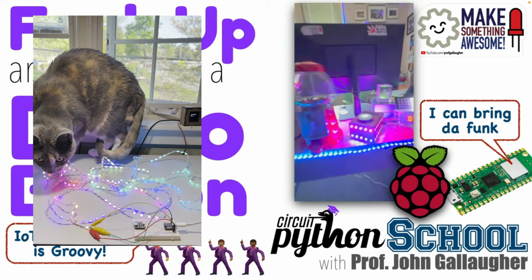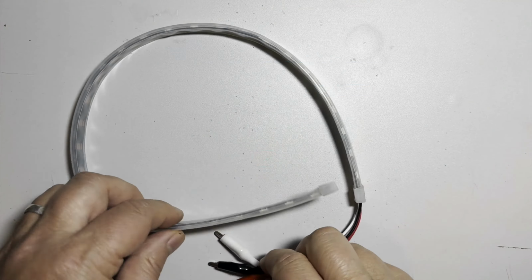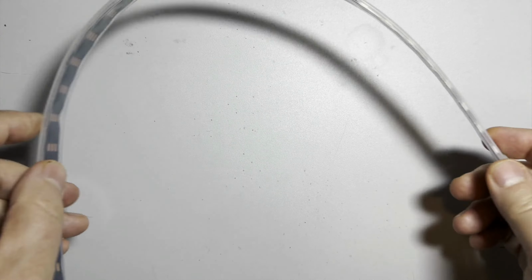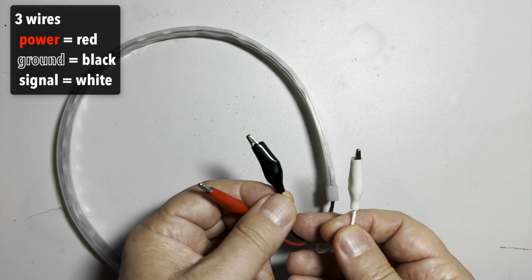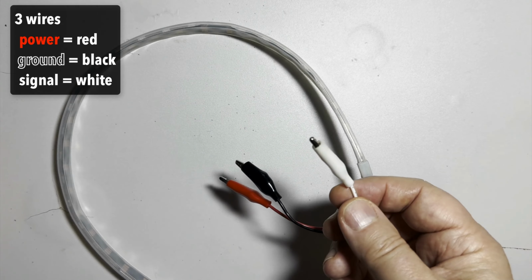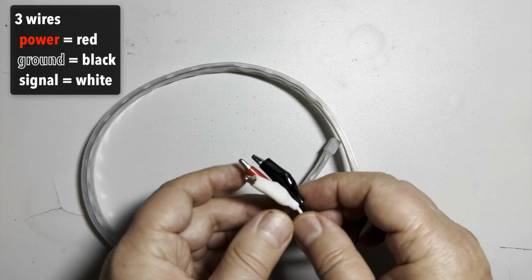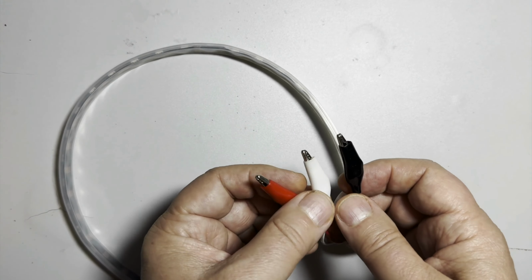Now, when you're ready to learn more about NeoPixels, you can check out Adafruit's NeoPixel Uber Guide. Now, the standard RGB NeoPixel strips and strands that we're using have 3 wires with alligator clips attached to each end. The red wire is power, the black wire is ground, and the white wire is the data wire that's used to control our lights. The colors won't always be the same on your strip, but standard RGB NeoPixels will have 3 wires, 1 power, 1 ground, and 1 signal.